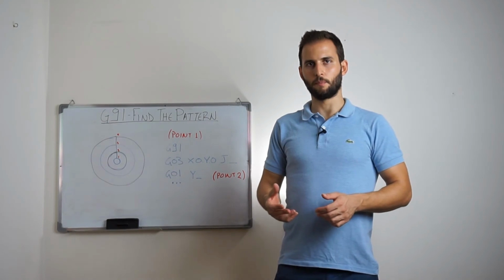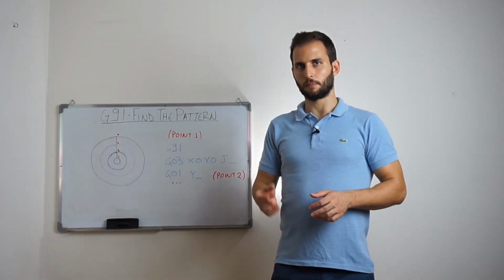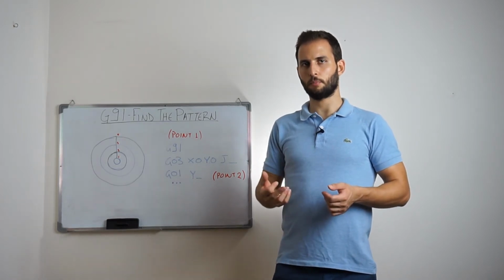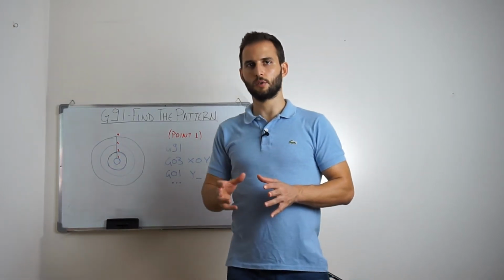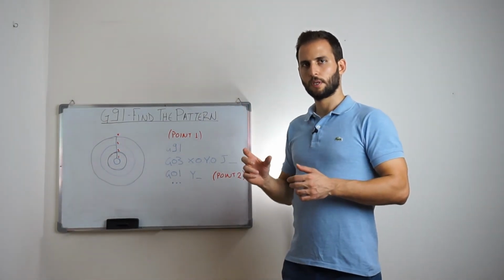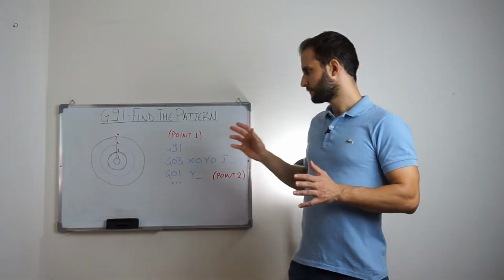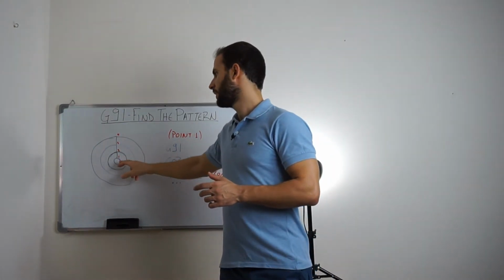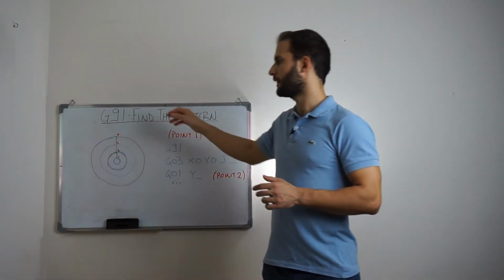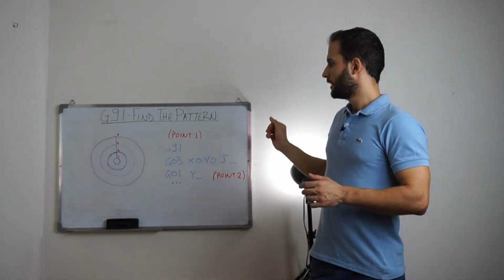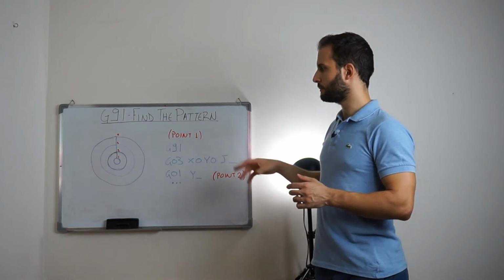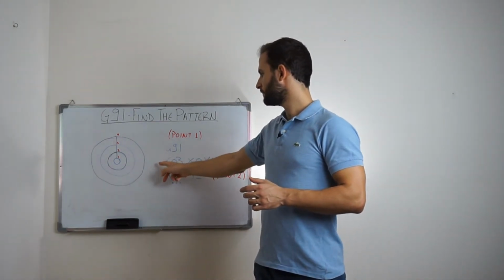An additional example that can be programmed using G91 is where we want to machine a circular pocket. This is not the kind of example that can be machined using identical blocks, but as you can see here, we can see a pattern. We have circle and line, circle and line, circle and line, and it goes on. As you can see here, the basic two blocks that are repeated again and again are a full circle and a line.